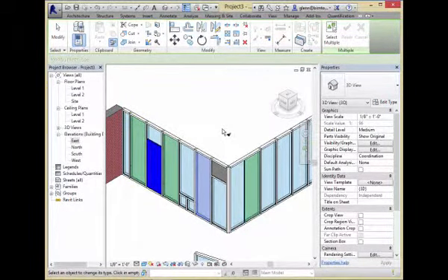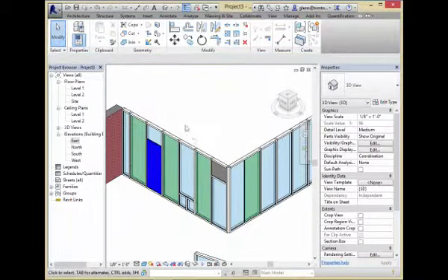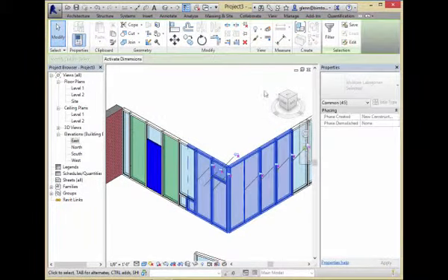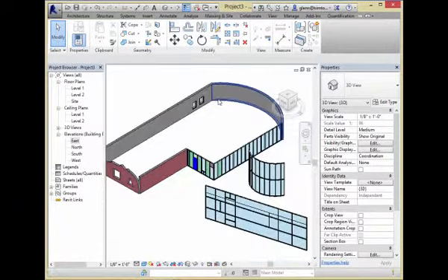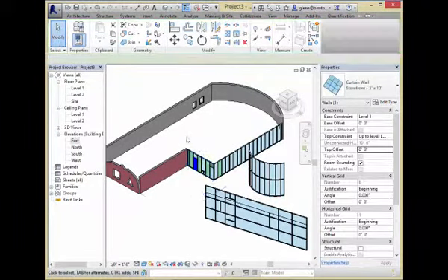So you can quickly get things. Again, the problem I was having was because they were all pinned, it wasn't going to let me go through and change things because they were pseudo locked. So the way I got rid of that was I just chose a whole bunch of objects and said unpin them all. That opened them up temporarily. We could pin them back again later. So let us just pause there for a second. Again, copy it across if you want to, but let's do this.